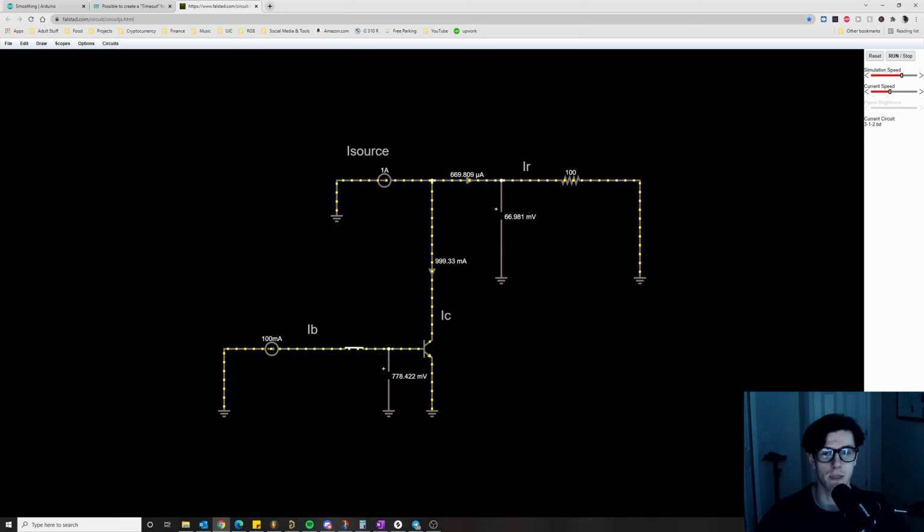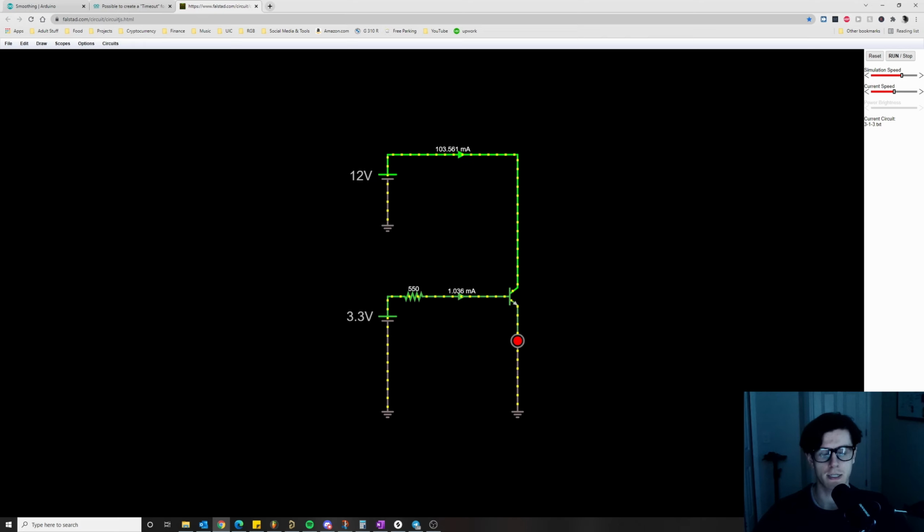All right, so these are some of the limitations of transistors, and we'll get into more of this later, showing some of the applications, but I just wanted to demo this fact. Okay, so this next one is a really common use of transistors that you'll see on YouTube, which is just to control the current through an LED. It's a pretty good use of transistors because it's easy to control the current through this LED using a simple voltage and resistor setup.